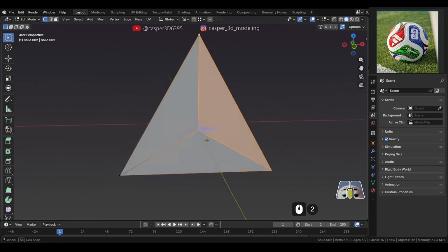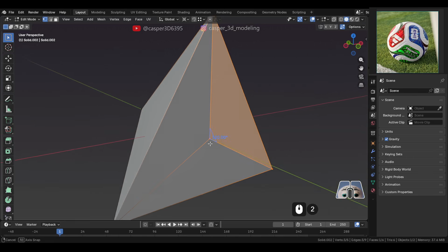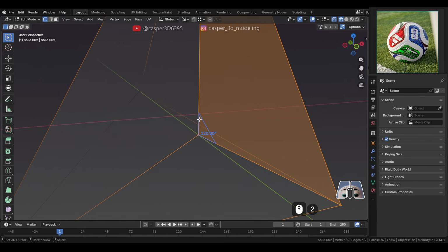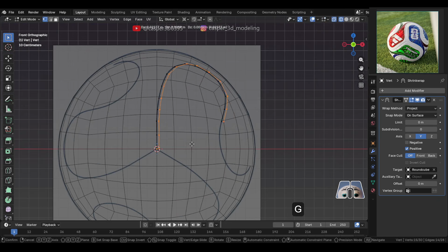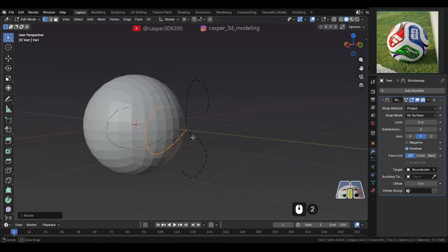All right, let's look at this triangle face. You can see 3 lines coming right out from the center, same as the pattern. And as you can see here, the exact angle between them is 120 degrees, which is shown when I calculated it with the Measure It tool. So that's the same thing we need to do here for this pattern. Rotate this copy by 120 degrees. Then duplicate it again and rotate another 120 degrees. And that gives us the pattern perfectly.